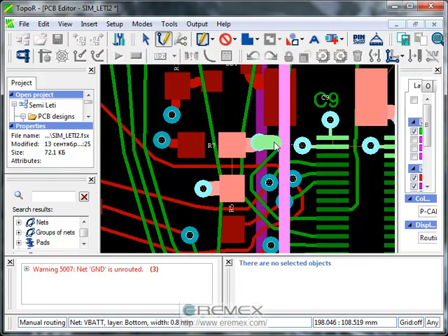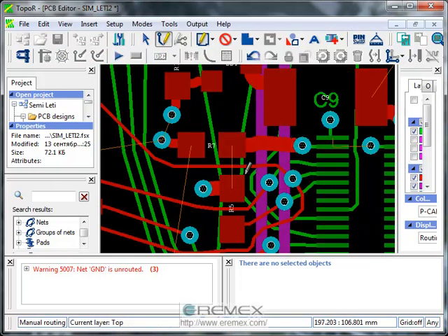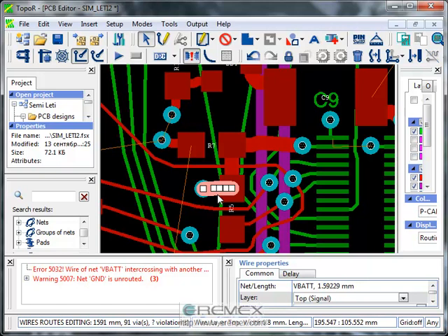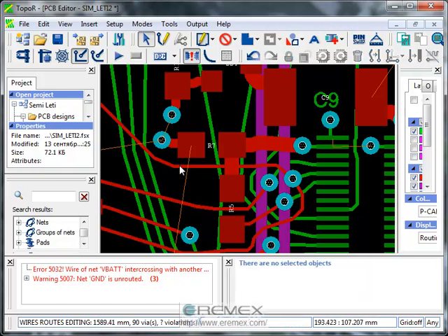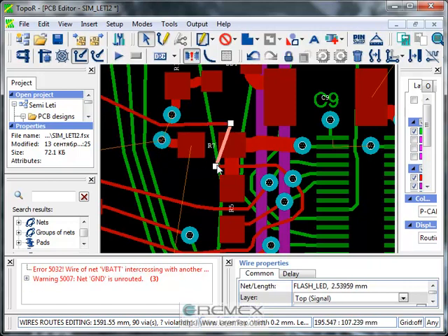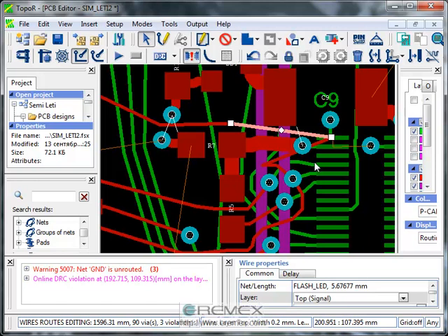Connect the resistor pad to the via that is attached to the copper area. Use the L hotkey to change layers. Remove the extra via. Select a wire segment and press X to select the entire wire. Remove it by pressing Delete. Select the segment of a crossed over wire and move it elsewhere by dragging its markers.